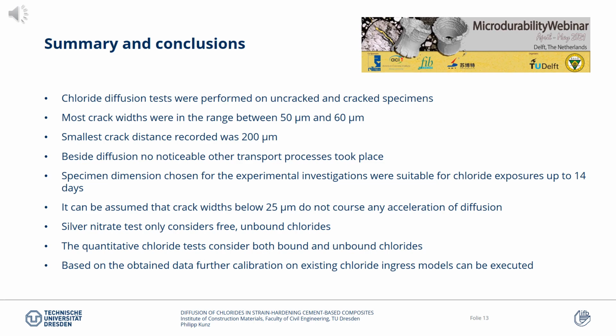Based on the qualitative chloride profiles we observed with the silver nitrate tests, it could be assured that besides diffusion, no noticeable other transport process took place. And it was found that the dimensions chosen for our experiments were very suitable for chloride exposure up to 14 days. Qualitative tests themselves yielded no accelerated diffusion in crack-free regions. Thus, it can be assured that crack widths below 25 micrometers do not cause any acceleration of diffusion, which actually underlines the findings of some other authors regarding that item.